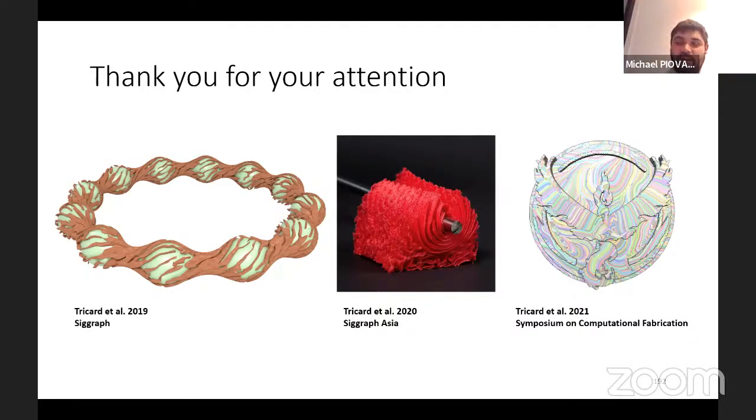And how was the printing time affected by changing the structures? Well, it's hard to say, because at first we had quite some trouble printing 85A filaments, because the extruder was always stretching the filament, the flow was hard to control, and so on. So at first we had to reduce the speed a lot to get our results. But now we have gained much more experience with our engineer on printing with this kind of filament, and so now we are able to print much faster. But at first it was fairly difficult to print.